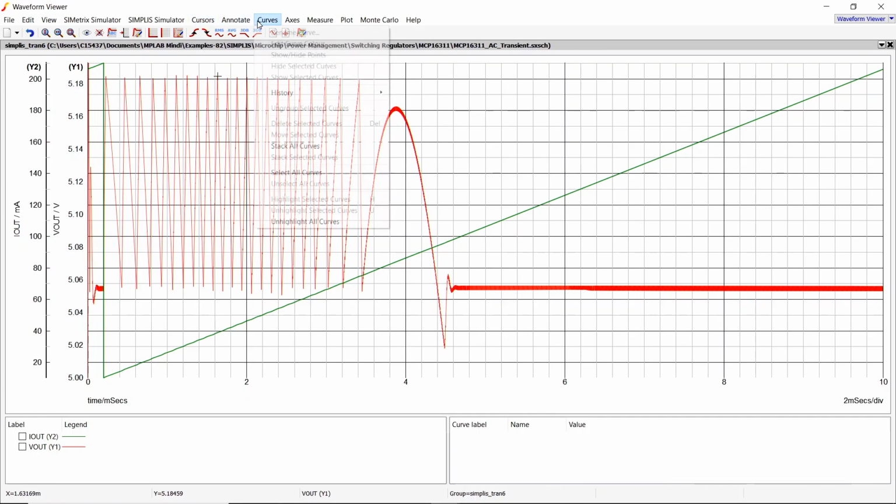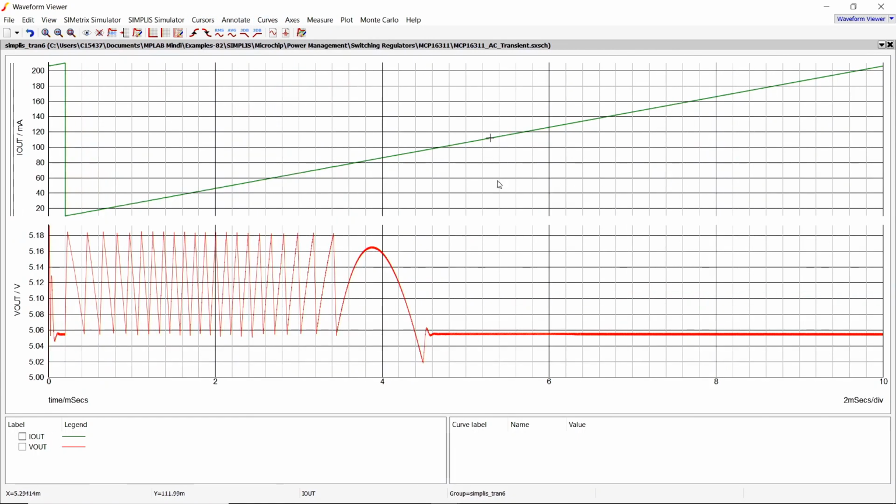But before we do that, let's stay true to our principles. As this load changes, see there's a transition point. Up until that point, under light load conditions, you see this ripple on that Vout? This could freak people out. So we want to make sure that in your design, can you handle this ripple? Is that okay? And that's the design decision that we're trying to make here.